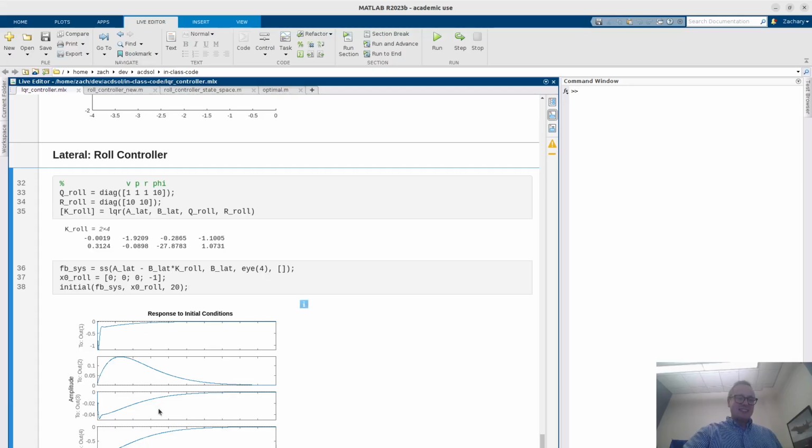and dampens out the Dutch roll mode, and does great. So that was 3 lines for 2 lectures of doing this by hand. So that's why LQR is so effective, because it simplifies the task of the engineer a lot.